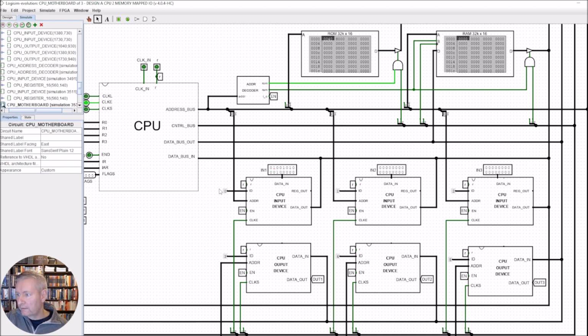So if we click on this here, you'll see that we've got a constant, and it's a 4-bit constant, and I've just made them all zeros. So this is device 0. Whenever we're trying to poll or talk to device 0, it will come down here. So when this is equal to this, one of the enable line options is going to go high. Now the other one's going to come, as I said, from the IO.